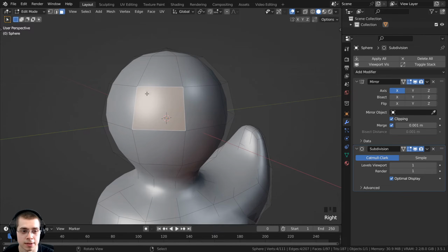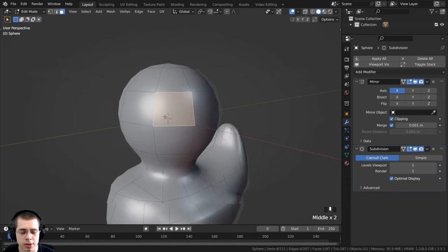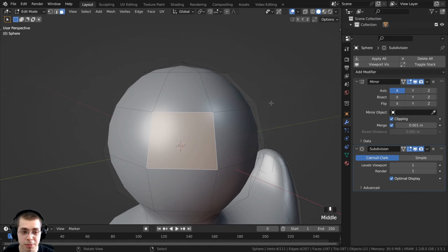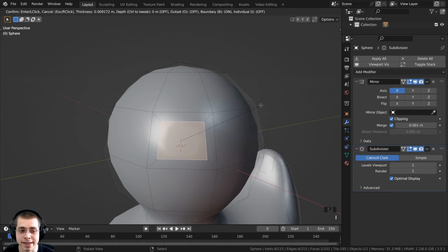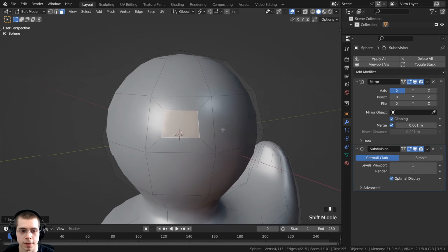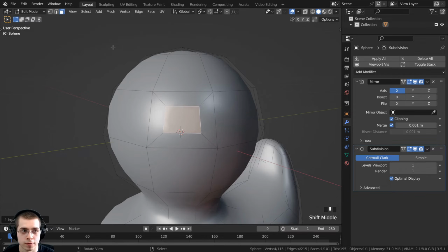and I'm going to select this face right here, so it's the face which is going slightly towards the front. And I'm going to press the I key, that is going to inset the face, so we now have another face in that face, and I will bring it down and place it there. And then I want to shape this so it is a more even square.